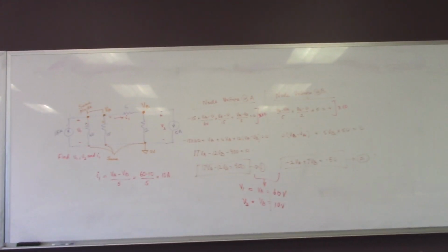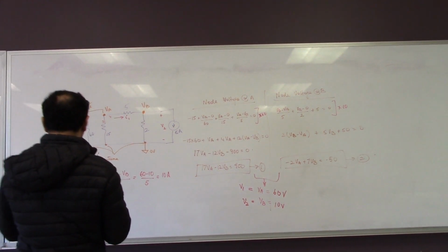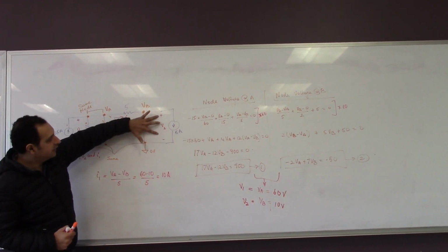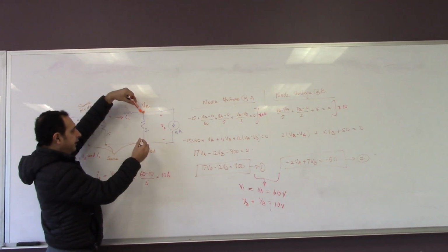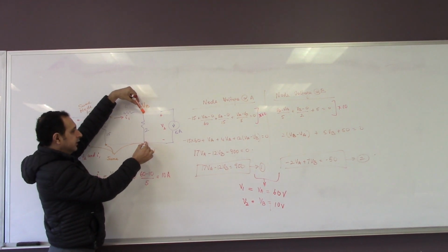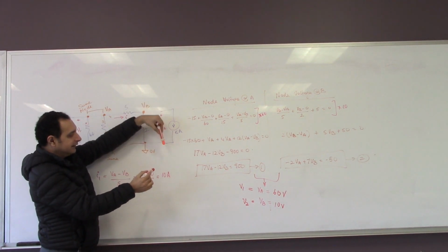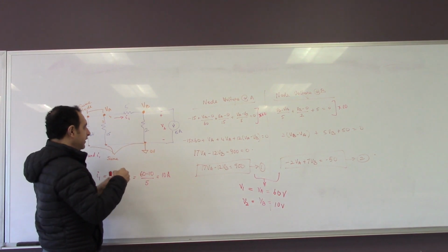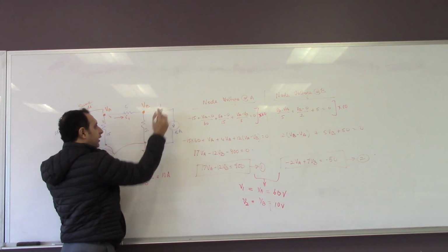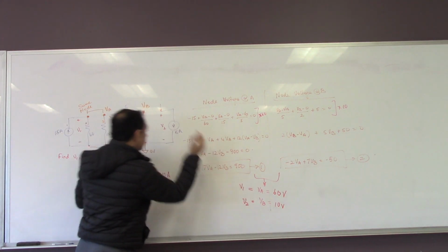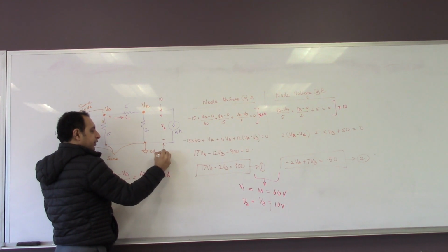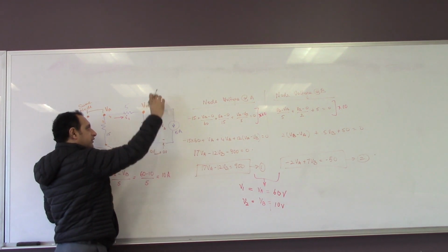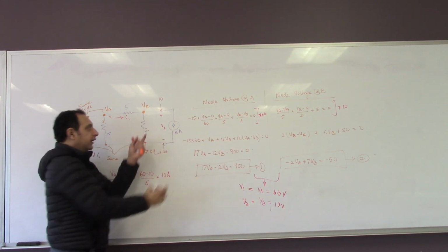Can I move the V1 and V2? Okay. All right. So if you look here, V2 is this voltage, right? So just as you guys did with your experiment, if I'm measuring V2, I'll be measuring like this. Okay. So this is positive and this is negative, right? So the voltage at this end is VB. What is VB? VB we know is 10. Voltage at this point is the same thing that we assume, 0 volts. Okay, so the total voltage is 10 minus 0, which is the same thing as VB.